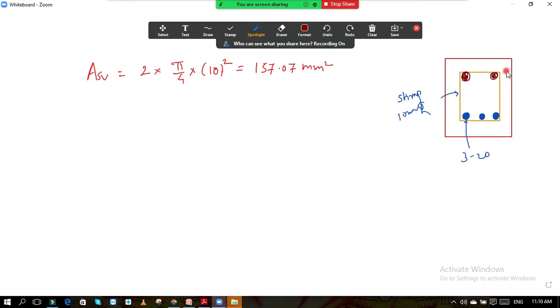Okay, so as per the IS code, for the earthquake, 13920. Okay, so here minimum 2 bars of 12 mm should be provided. These are very important things. I am telling you the clauses from IS codes also, other than IS 456 2000. So this clause is not given in IS 456 2000, but as per the design of earthquake resisting structure, if you want to design a structure which is earthquake proof, okay, then minimum 2 bars of 12 mm diameter you should provide at the top.